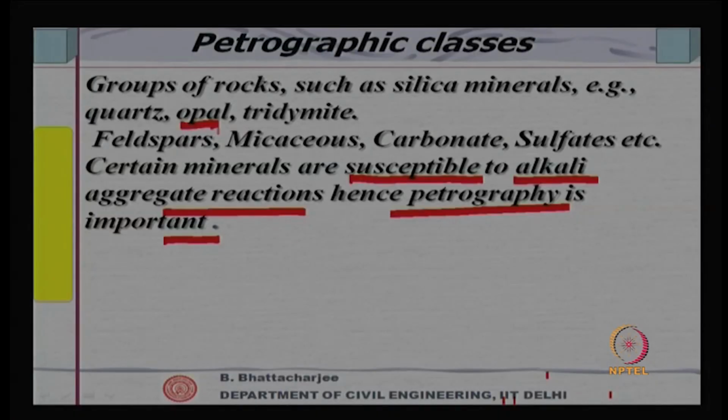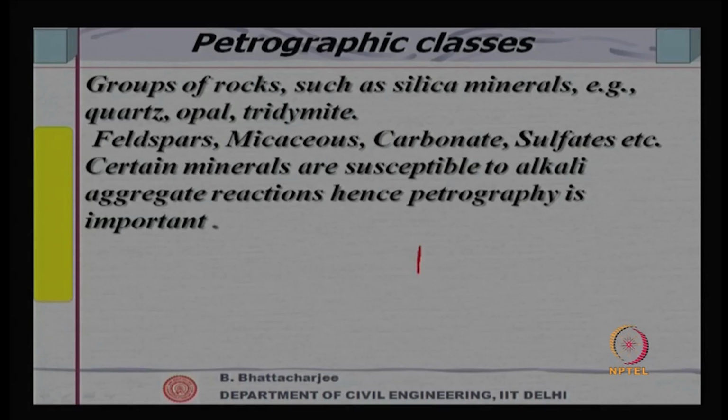Recall, in the first slide itself I said that aggregate must be inert, it should not react. Now, certain types of silica such as opal can react with sodium or sodium hydroxide, finally, of course, in presence of water, and form a kind of gel.